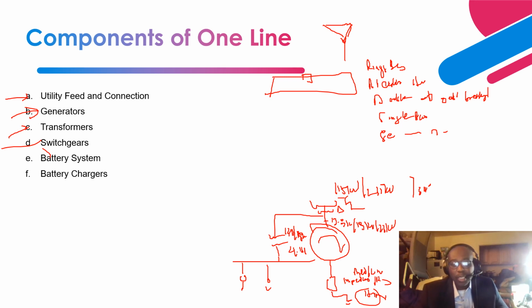There are so many configurations of the medium voltage switchgear. We have a double bus with a tiebreaker, or a single bus, based on the criticality of the load. Then you can have battery systems. The battery system is basically the DC part of the one-line. It provides DC voltage to all the critical equipment, to include relays and annunciators. All these devices utilize DC voltage.